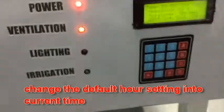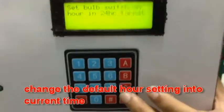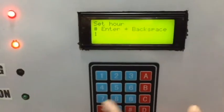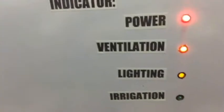The ventilation consists of one exhaust fan and one intake fan. It will be used to maintain the required temperature and humidity of the plants inside the greenhouse. For the lighting system, by pressing its mode the user needs to change the default hour setting into the current time, and that is 3 p.m. so the user needs to input 15, because it is in 24-hour format.